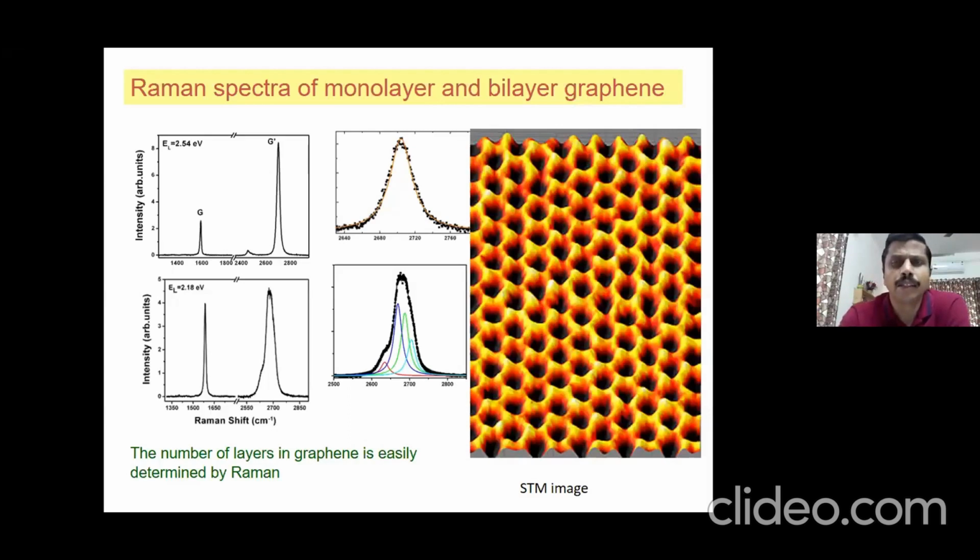So usually graphene is characterized using Raman spectroscopy. We can use either Raman spectroscopy or any electron microscopy technique to characterize the graphene, but the commonly used technique is Raman spectroscopy. If graphene is formed, you can expect the G band, the G prime band, and you can see the 2D band, etc. So depending on the quality of the graphene, you can see the ratio.